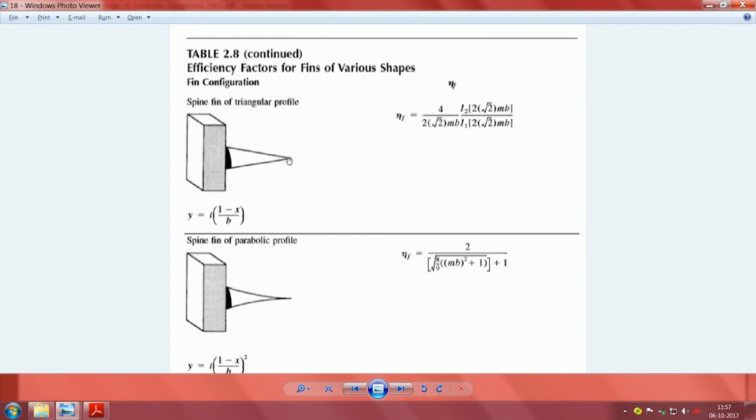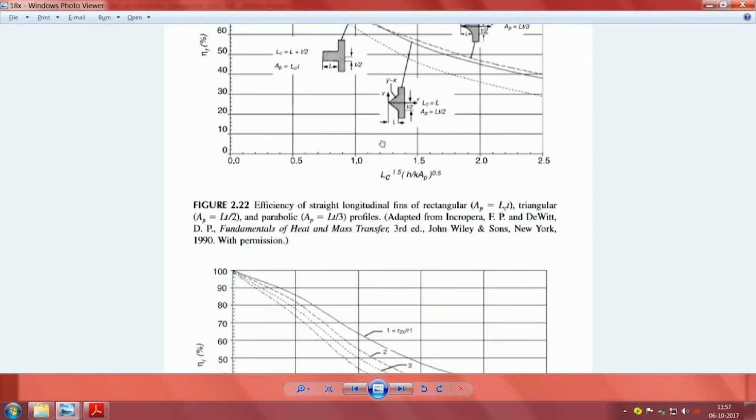In case you do not have such a device and you wanted natural cooling, probably you can have a heat sink which is extruded with tapered fins. At least in one direction there may not be a spine fin, it is a tapered fin, and in the other direction you make spaces, and sometimes it is done at an angle. We still have the advantage of having a lot of these things.